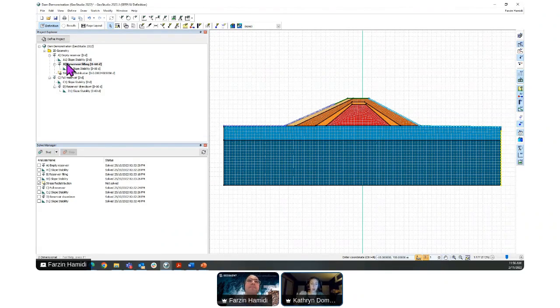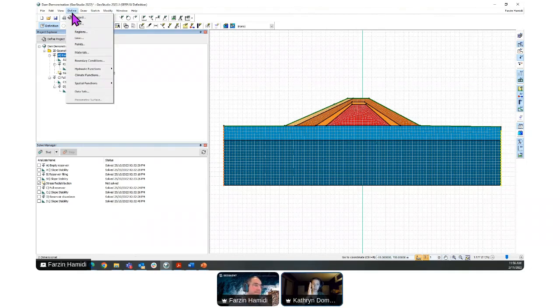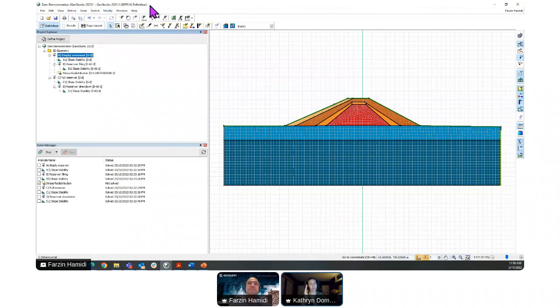In that case, if you wanted to set up initial conditions before you start your transient analysis, typically when we look at groundwater profiles in the unsaturated zone, it's kind of funny because we see that the average infiltration rate tends to produce a fairly constant pore water pressure value with depth in the unsaturated zone. It's a negative pore water pressure value in the unsaturated zone that's pretty constant or similar with depth depending on the material. If the material changes, it does shift around with material.